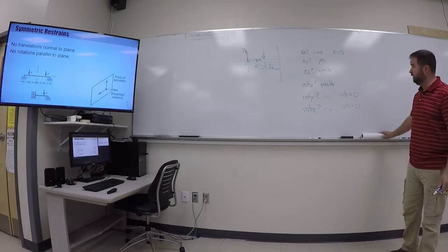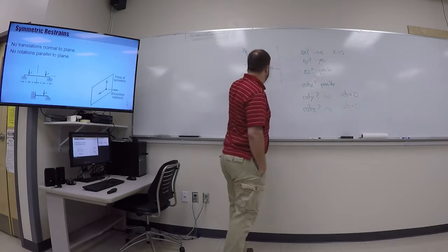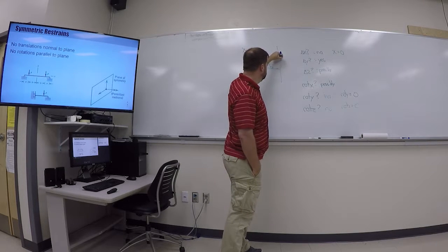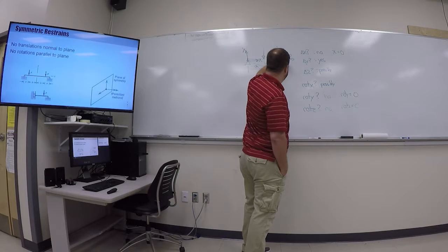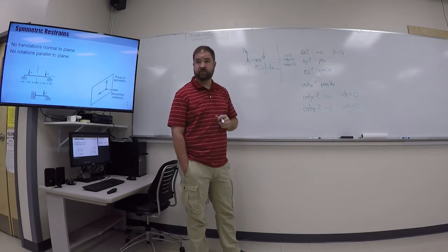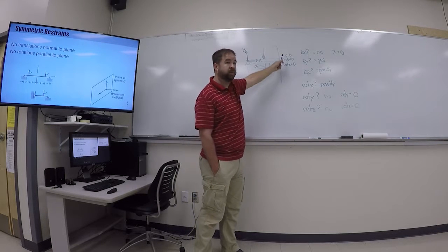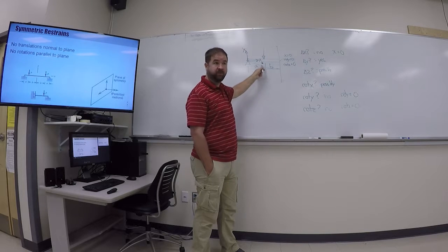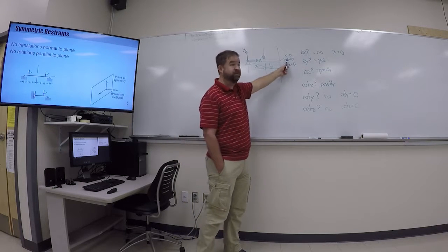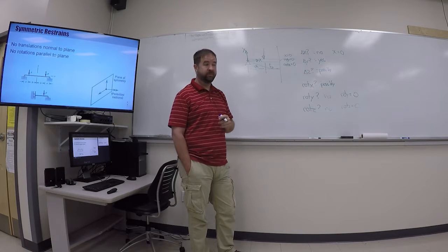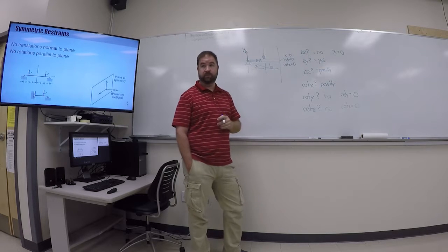So if I wanted to manually set up the constraints in Solidworks using reference geometry, if I had a line of symmetry, what we would do is model half of the geometry, and then I would apply the constraints on the end: displacement x is equal to 0, rotation y is equal to 0, and rotation z is equal to 0. And we can set up Solidworks so that we can specify exactly those constraints. Okay? And when I do that, then that is applying a symmetry constraint. And then I can model just half of this instead of the whole thing. Now, the honest truth is that Solidworks makes this easier for us because it has the ability to apply symmetry to a plane, and it figures out what those constraints are. But on a test next week, I might ask this question, and you need to be able to figure out which one of these are supposed to be 0 based on that plane of symmetry.